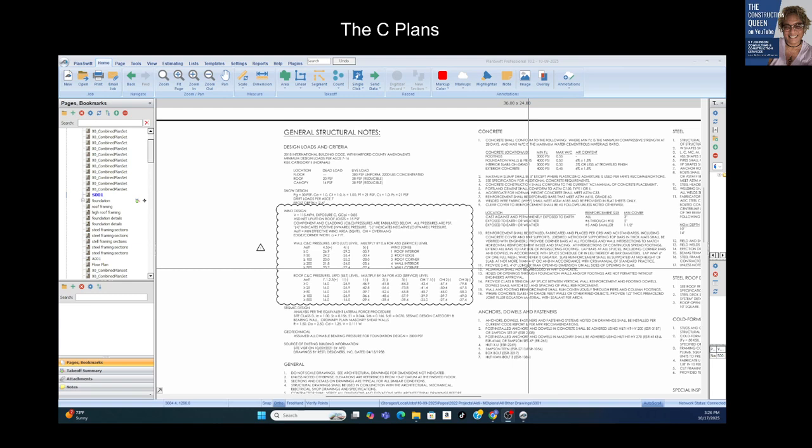And then we have environmental loads, okay, which are wind, hurricanes, earthquakes, seismic activity, and soil also takes into effect. So depending on the type of soil you have, it really depends on the type of foundation you're going to have to hold that dead load and all the live loads that come through, plus all of the environmental loads that could happen every winter.